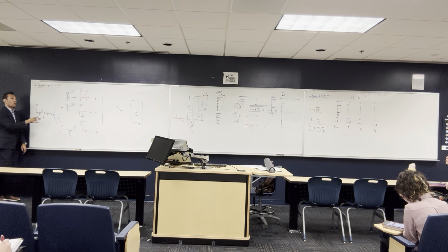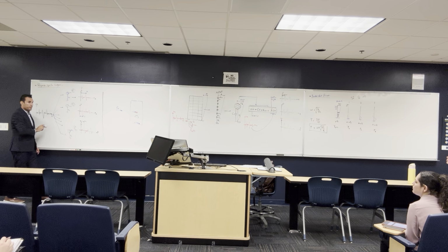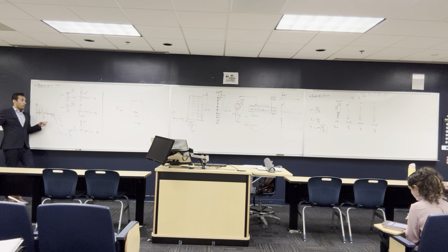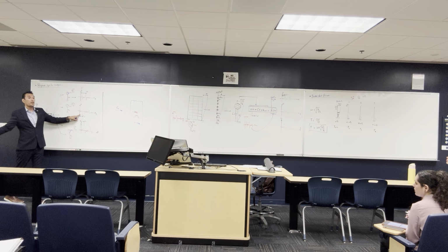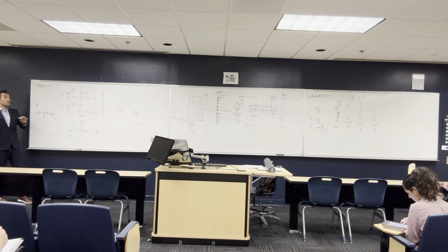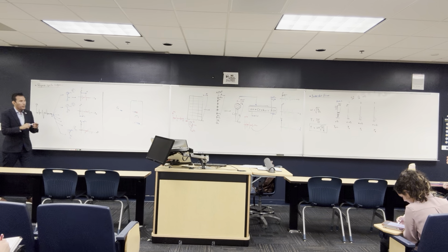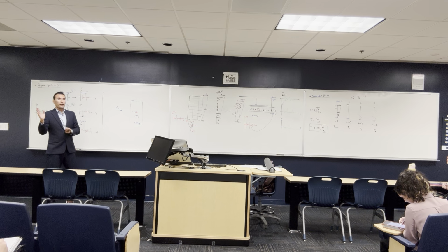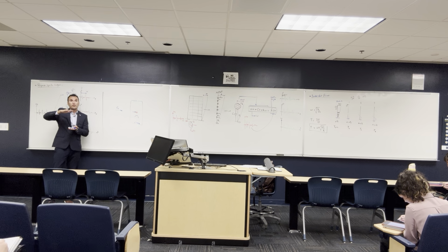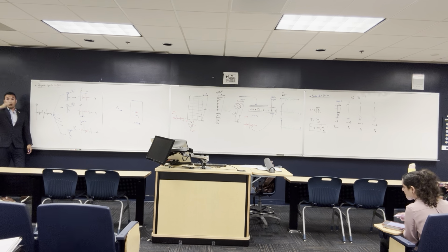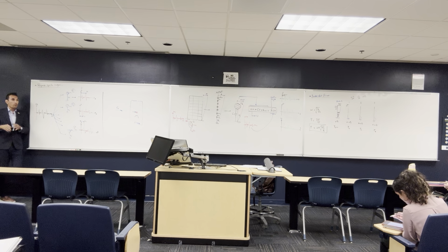By the way, tell me the difference between this and this. What is this graph and what is this graph? Both of them are acceleration. This is the acceleration of what? The ground acceleration that comes from the earthquake. And this is the acceleration of what? The building itself. Is every building going to have the same acceleration? No. The tall building is going to be different from the short one. What do you think, if a building is 50-story and another is 3-story, which one is going to have higher acceleration? The 50-story is long and makes a lot of displacement, but the short one is barely moving.